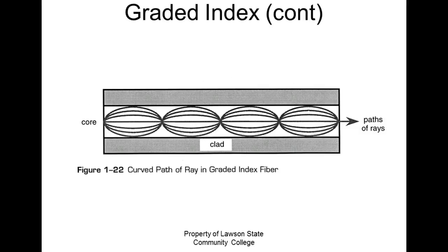It costs more. Graded index costs a pretty good deal, because you can see putting all those glasses in there together is going to be complicated. Getting them all the same size, keeping your ovality, your concentricity, you know what I'm trying to say, the core offset.